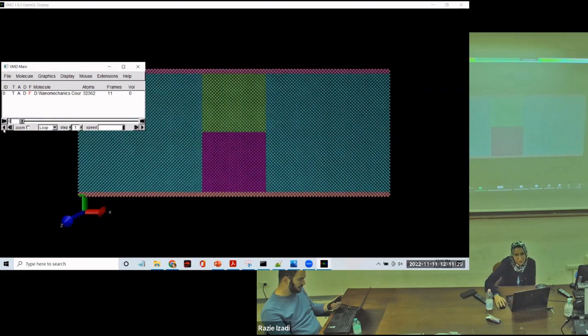In reality, for example, the crack is really critical for brittle materials because it starts and goes on. But for ductile materials, sometimes a crack starts, we have some yielding around it, and it stops. So even the stress concentration factor, if you're familiar with that, when we have an abrupt change in the geometry, is important for a brittle material, not a ductile one like metal.